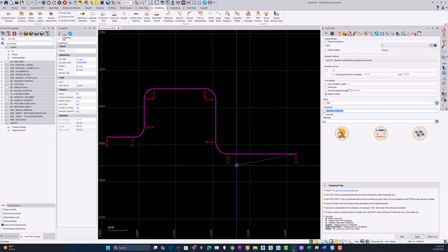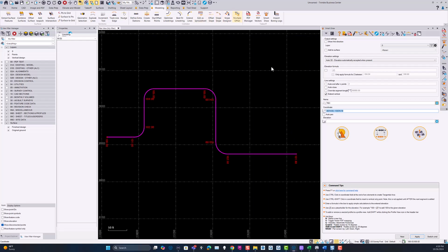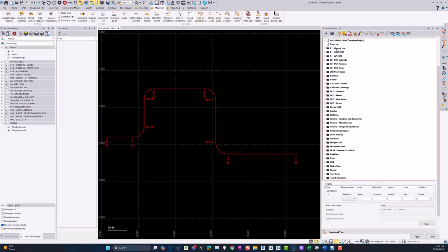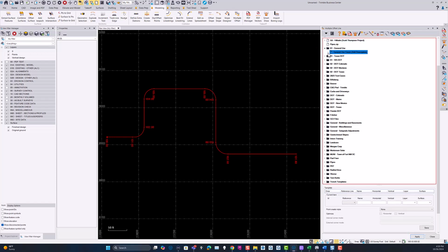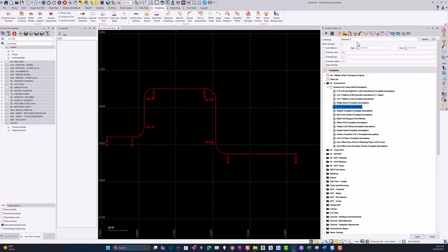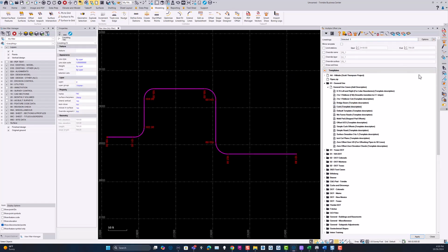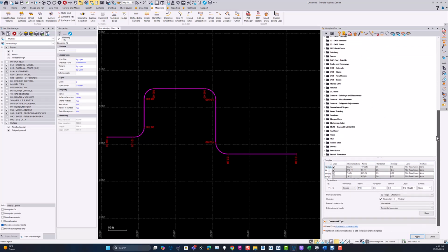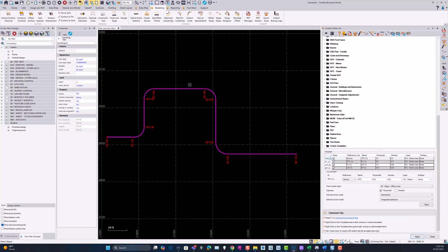Okay, so we've got a top backer curb line, and now let's say we want to run our multi-offset line command, so I'm going to run that up now. In multi-offset line I'm going to pick a template, which is my curb template. The curb template is set up for offsets to the right hand side of this line. You've got a series of offsets and a series of elevation differences or slope differences between the nodes to create the curb shape all the way to the edge of pavement.